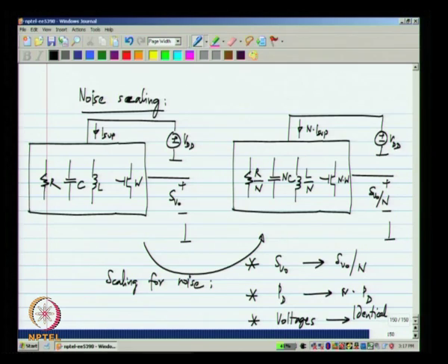Okay. The way to do that is to scale up the impedance of every branch by a factor n, that is we go from right side to the left side in this picture. Then what will happen is, the power dissipation will reduce by a factor of n, and the voltage noise spectral density will also increase by a factor of n. So, while saving power, the noise will increase, and let us say the noise of this particular circuit is not very significant. In that case, you can live with the increase in noise, but you will be happy to take the reduced power dissipation. Okay. So, you will go both ways depending on whether the power dissipation is important or the noise is important.